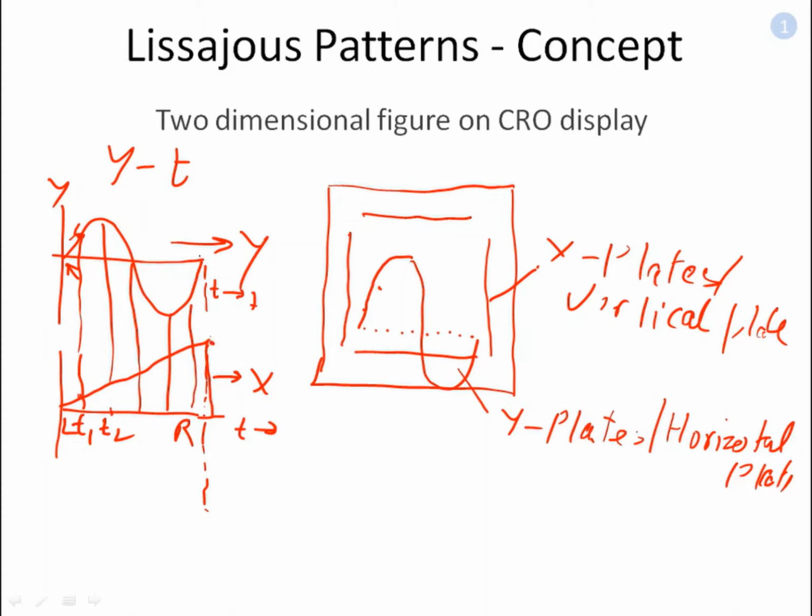So if the complete waveform is covered by the sawtooth waveform through synchronization, you will see the complete waveform. So by adjusting the bias, you can adjust it in such a way that the center line is at the origin like this. So you can have the display at this point just like this. This should be the display for YT.